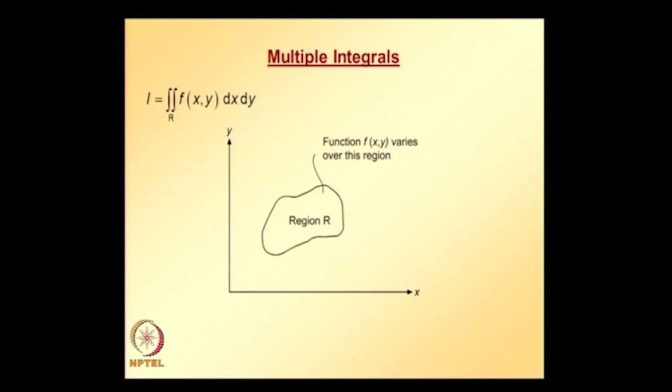So now basically what we require to do, we need to find this integral. We require to decide how many integration points we want to use along the x direction and y direction. So this integral f(x,y) dx dy is approximated as the function f(x,y) evaluated at a certain number of points along the x direction and y direction.